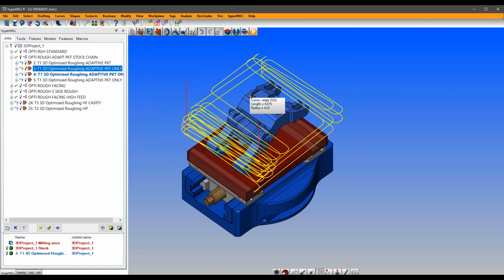Straight line movement ensures that your machine is getting up to speed, okay? When we look at trochoidal toolpaths, you're making good use of the flute length, so tool life is going through the roof, for sure. But the dynamic that your machine requires is very high, okay? Certainly when machining aluminium, surface speed is going through the roof here. It's increasing. I've seen 9-10 meters a minute from tooling. Every movement is an arc movement in trochoidal and requires heavy dynamics from the machine.